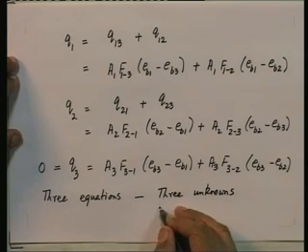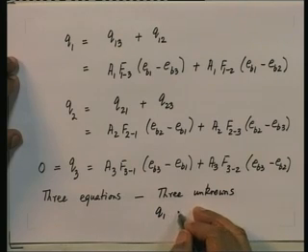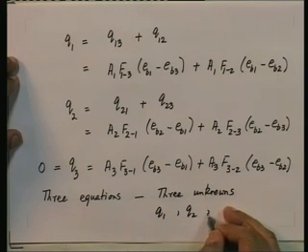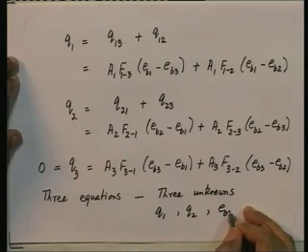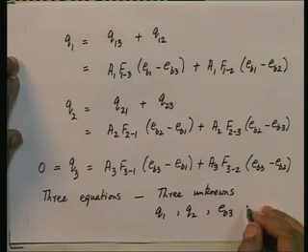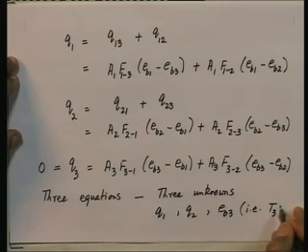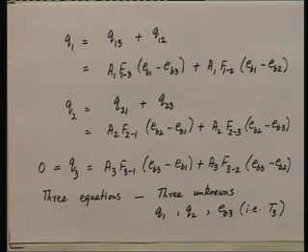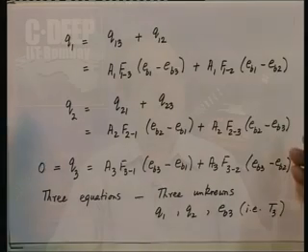And what are my 3 unknowns? Q1, Q2 and EB3. EB3 is nothing but sigma T3 to the power of 4. Instead of writing sigma T3 to the power of 4, I am writing EB3. So, I have got 3 linear equations in 3 unknowns. Solve for them and I will get the quantities Q1, Q2 and EB3. So, it is a very straightforward problem which we have.